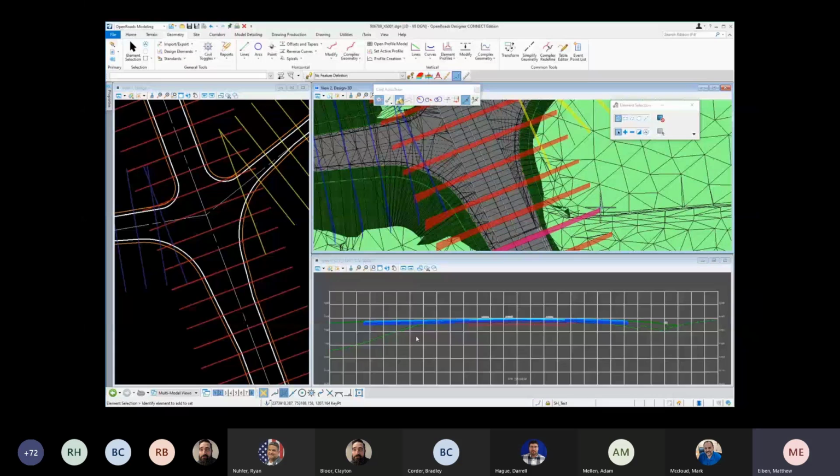And you'll see that when you cut your sections. This particular one looked like that was put in right at 1205. But this other one I'm snapping to right now is at 1207.16, which, that's just the way the software does it. So the reason I'm pointing that out is you're going to want to take note of the elevation that you want the top of this boundary to be at, whether you're trying to match exactly what was already created or you want to change that elevation. So at 125 here, my Z elevation is 1205. What I'm going to do, though, is I'm going to change that to like 1208, just so you can see what happens in the drawing model here.